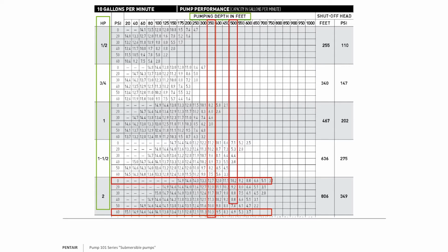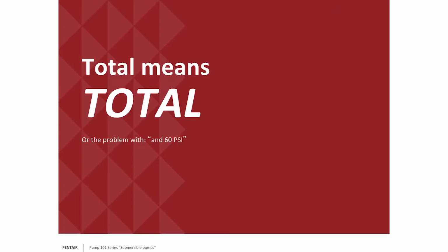But I myself, especially with smartphones and other things, find it very easy to calculate the friction loss now. I would rather you do it the total dynamic head way, which is you calculate everything out. Now, remember, total means total.